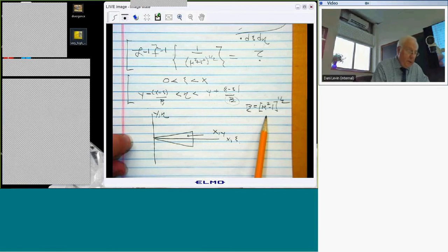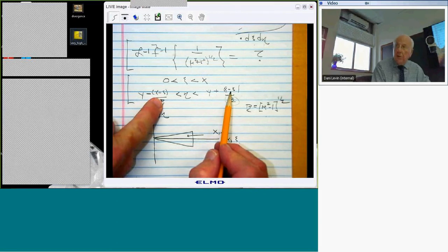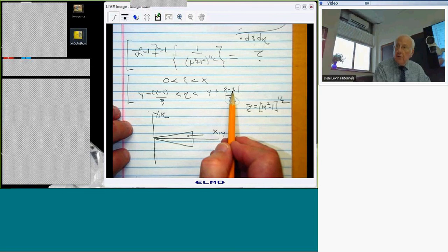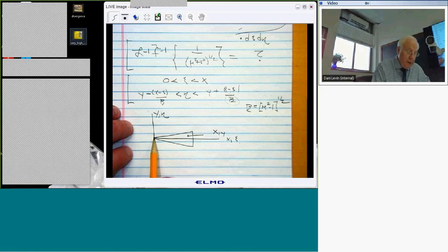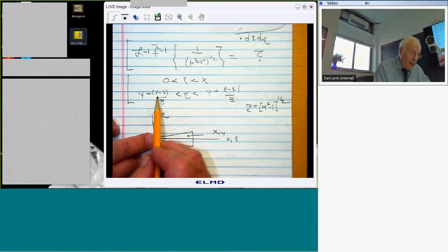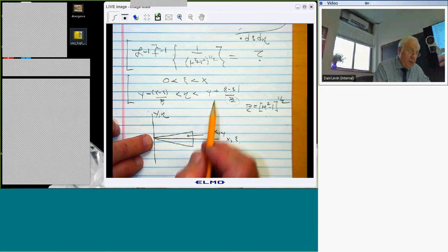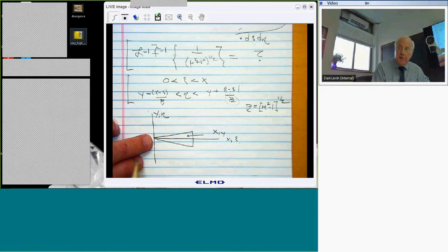And what happens when c actually reaches the x point? This term goes to 0, and the integral is over a point, just y. But on the other hand, when c equals 0, when I'm up here, I integrate from y minus x over beta to y plus x, also over beta. And so I can draw the line using my limited artistic ability. I am going to cleverly choose the Mach number so that beta equals 1. All right?